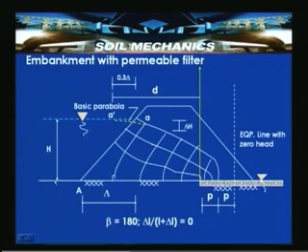So, H is the head on the upstream side now. By using Casagrande's approximation, this is 0.3 times delta, where delta is the horizontal distance from this upstream point A to the point where this head meets. So, this point here is approximated as 0.3 delta. This particular portion is called the basic parabola.